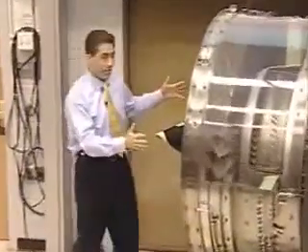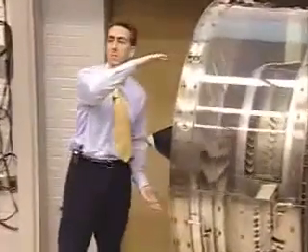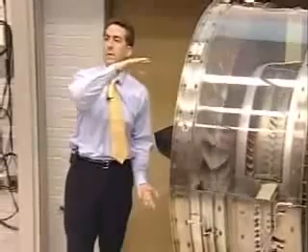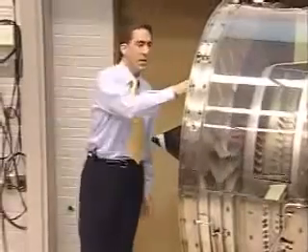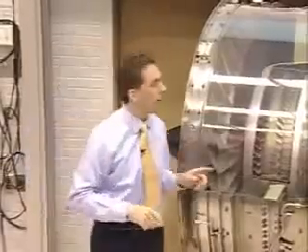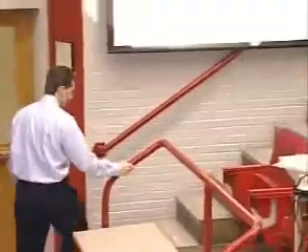You have zero angular momentum coming into the engine, and these blades then cause it to have some angular momentum. Right? So it's the axial flux of angular momentum that relates to that torque. And then to connect that to the power, you multiply it by the rate at which you're doing work. So that's the rotational rate.